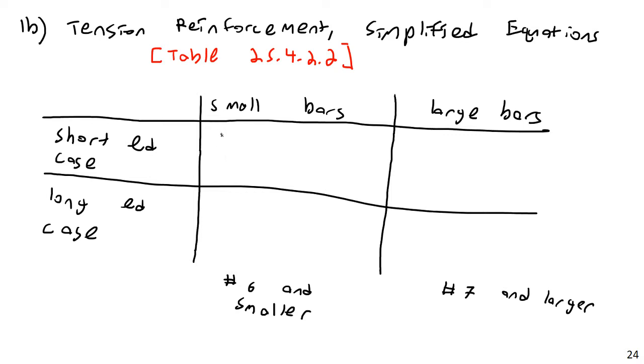But here, the formula is going to be, say, 1 over 25 times a factor fy, psi t, psi e, and these are the exact same things we already talked about previously, divided by lambda root f prime c, times the diameter of the bar.